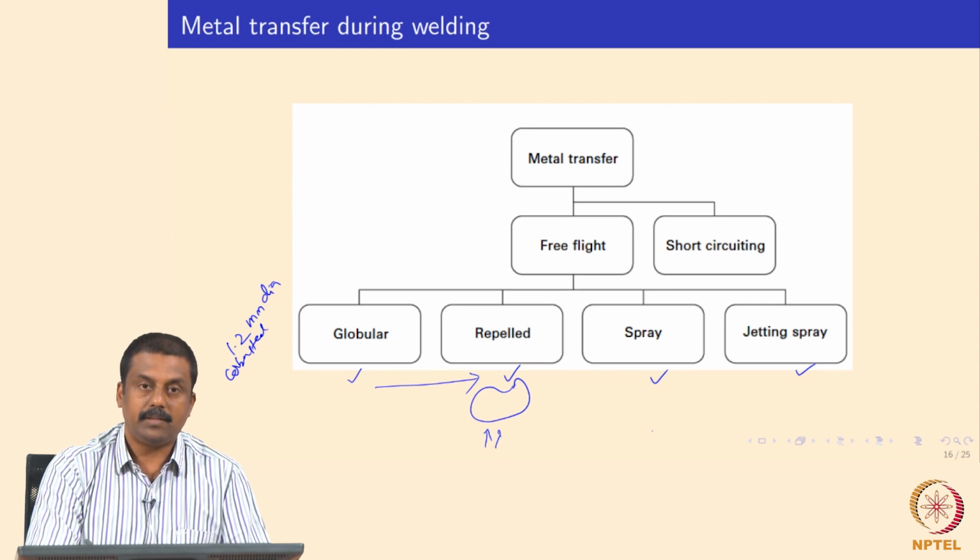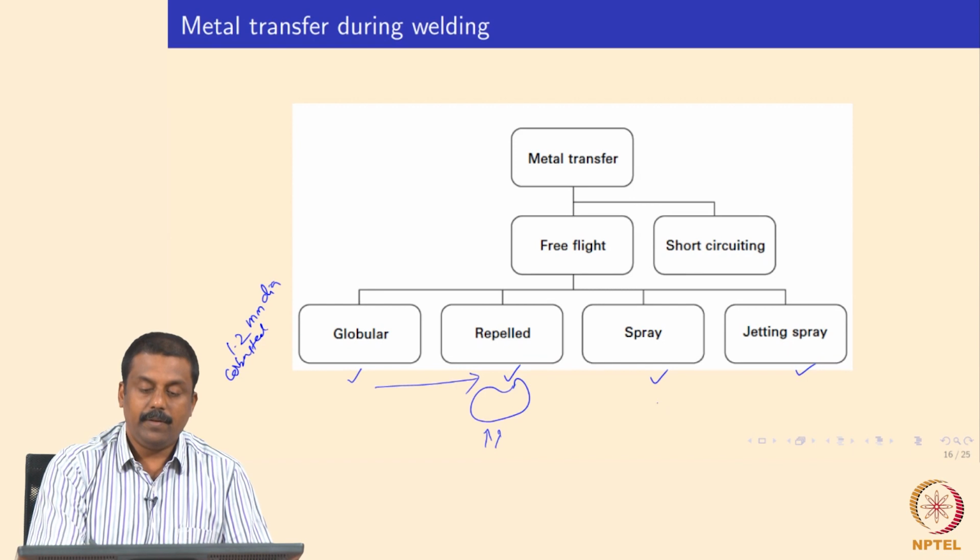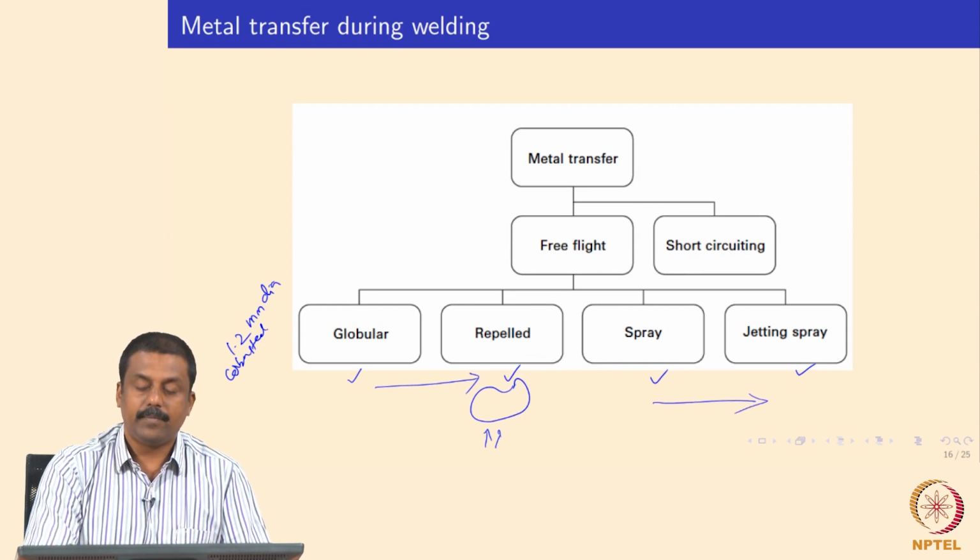And if you have a continuous spray of droplets with a diameter similar or smaller than the wire diameter, you can transfer the droplets to the workpiece uniformly without any spatter. And of course, because of the increase in transfer rate, you will also have very good productivity. So if you increase the current even further, you also increase the melting rate of the electrode, you end up melting more, and you also reduce the droplet diameter significantly.